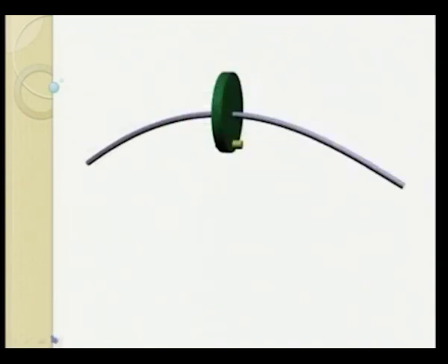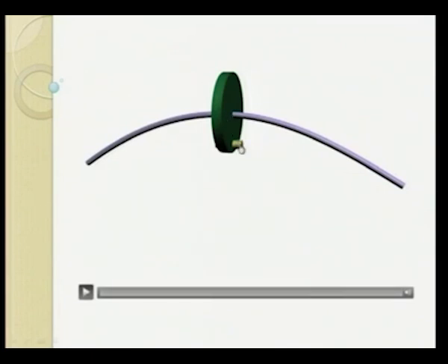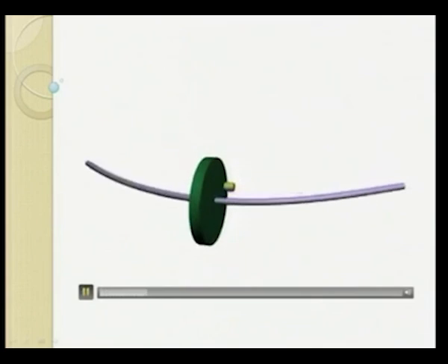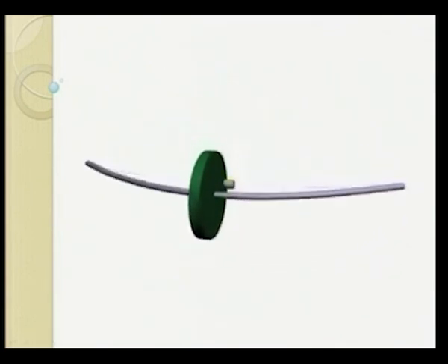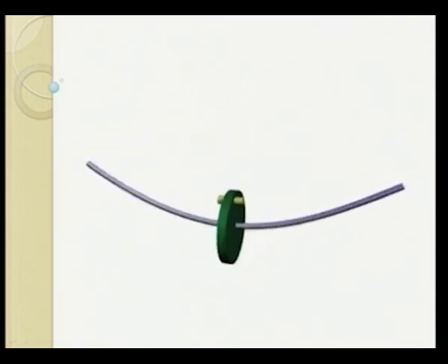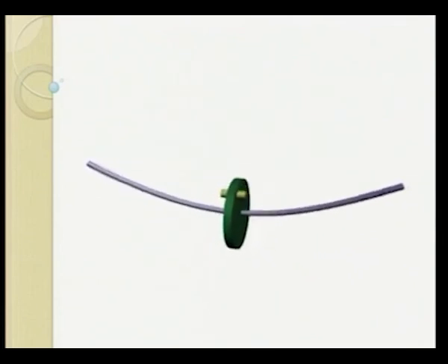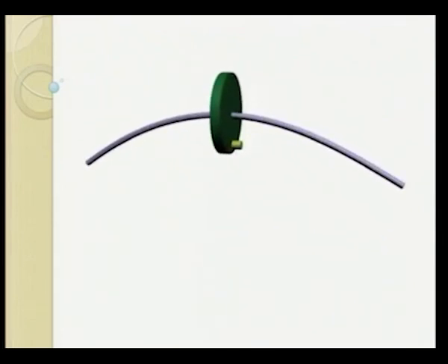And this one is another case in which we have crossed the critical speed, and in that case the unbalance will come inside, toward the bearing side. This is the animation for synchronous whirl. So the unbalance remains and tries to rotate about the bearing axis.